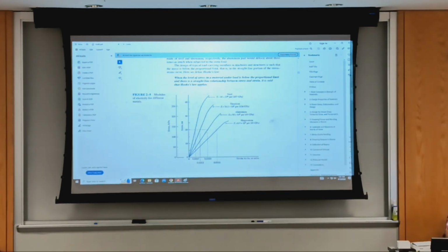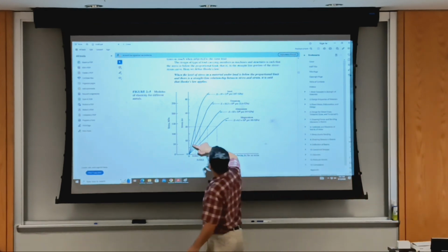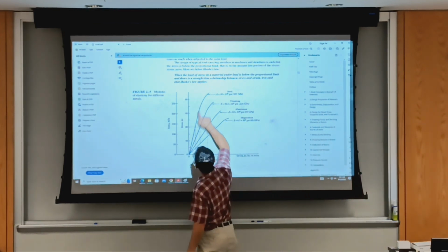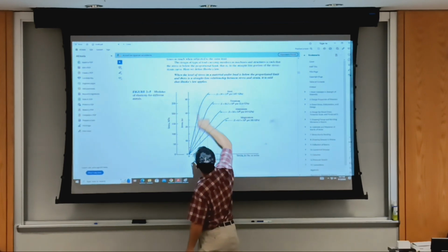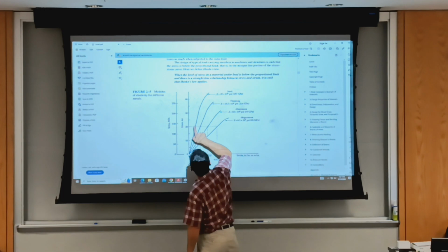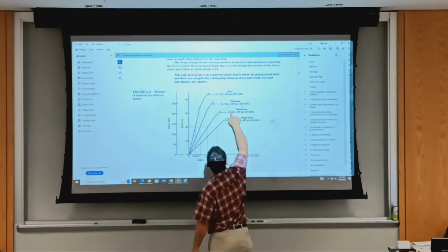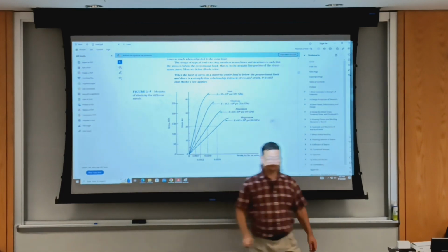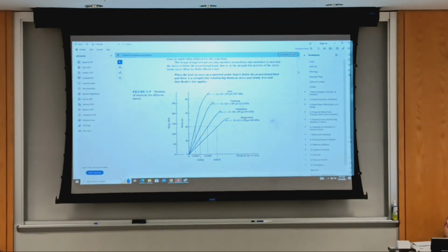And the stress strain curves for different materials are shown here. Being stiffer, it's steeper, that is, the slope of the stress strain curve over the proportional limit is higher for steel, less for titanium. Aluminum is even less, and magnesium is, of the four, the least stiff. So modulus of elasticity for magnesium is substantially less than that for steel.